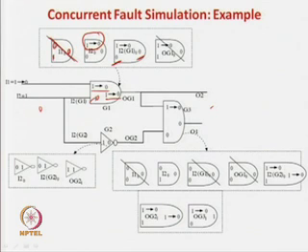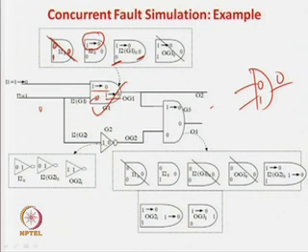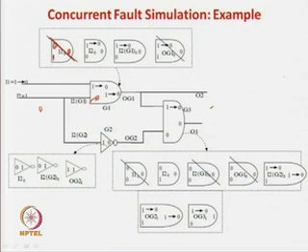There is a signal change because now the normal gate looks like 0 1 0, and here with the fault effect the gate is 0 0 0. So there is a signal difference over here. So this gate is going to be retained. Again you can see that this gate is retained. So, what are we doing over here?